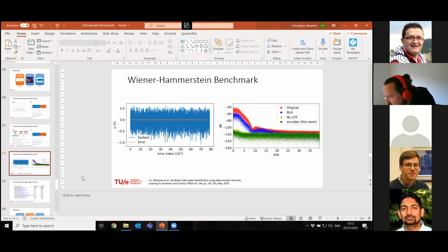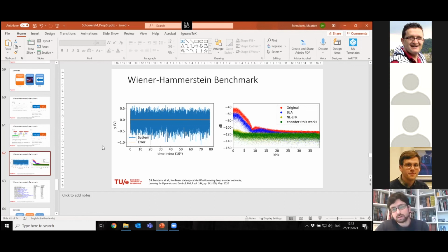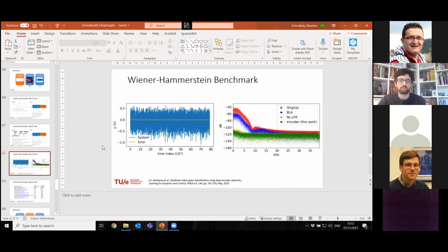How do you choose T for the horizon? That's the question of Philip. Currently it is a bit of black magic. Well, it's fairly robust. We analyzed that, and in the end it's fairly robust how you do it. If you want to go towards simulation error, then just take a couple of times the time constant of the system.